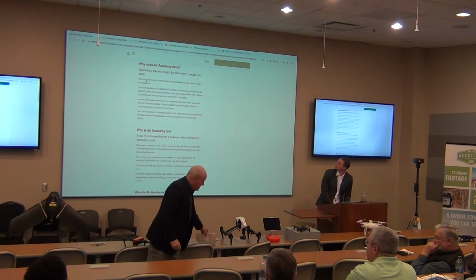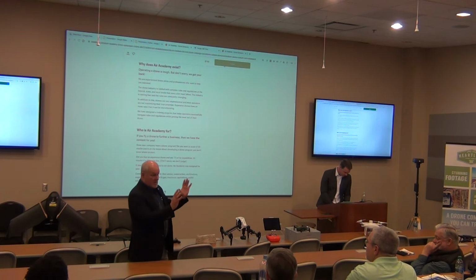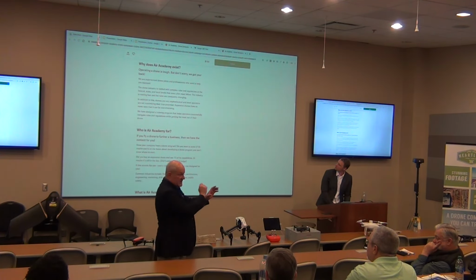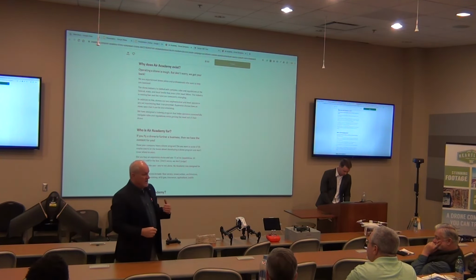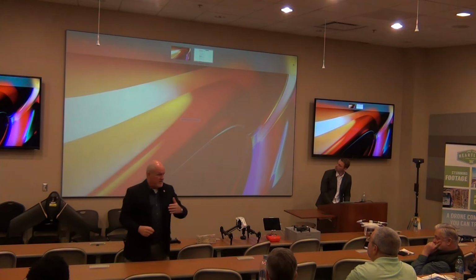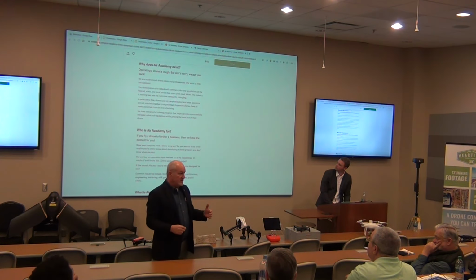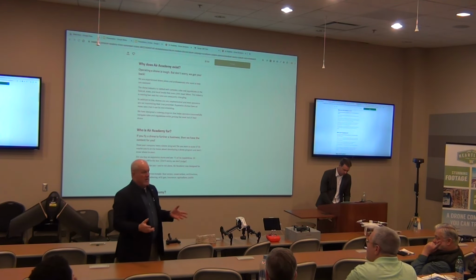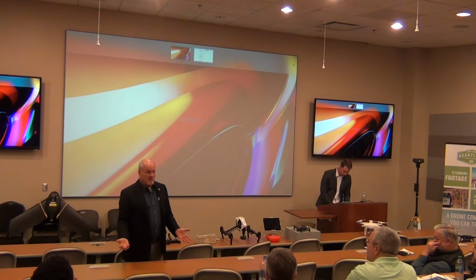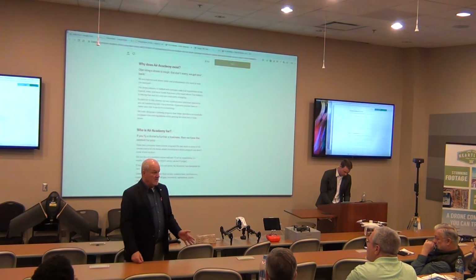And the engineer was able to take a man lift up using a map that we created, stitching these photos together, and tap on the exact stones that showed this anomaly. Rather than going around for 3 weeks tapping every single stone on 25,000 square feet, he was able to ground truth 25 stones and then declare the whole project shut down, ready to demo.